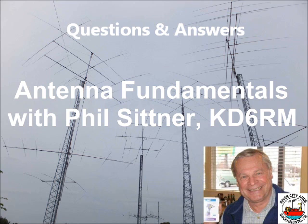I've got two. This is 2 to 1, 4 to 1, 6 to 1, 8 to 1. I really screwed this up. I changed this. Should have stayed at 1. But you can see as you change frequency where this is. And then on the Smith chart, point number 3 is clear down here, which means the antenna is way too short